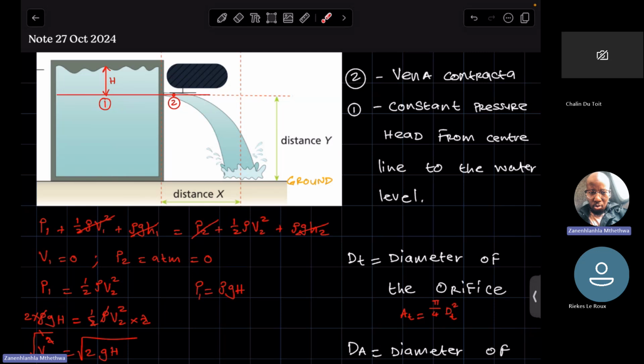So what I was saying is both the theoretical and actual findings are of this point, the vena contracta. Both the theoretical velocity and actual velocity are V2. The difference is when applying Bernoulli's between these two points from an ideal perspective, meaning not considering losses, then V2 is theoretical. But when applying Bernoulli's between the same two points, now considering losses, for instance frictional head losses, then we'd have plus rho g hf here. When considering losses, V2 is now the actual velocity. Are we clear?